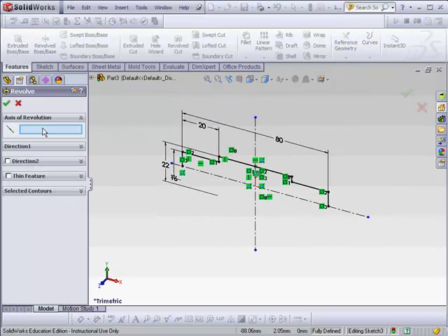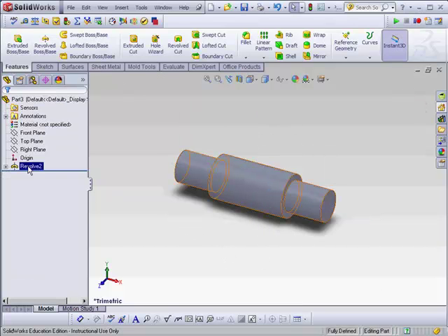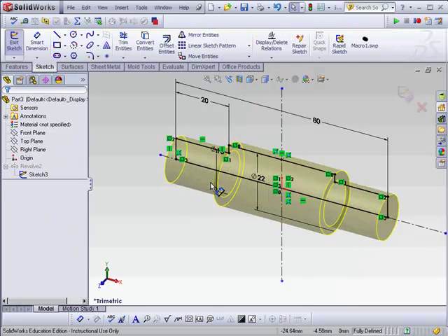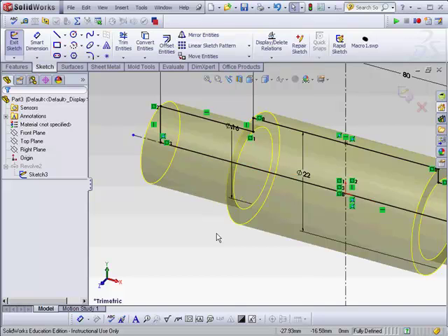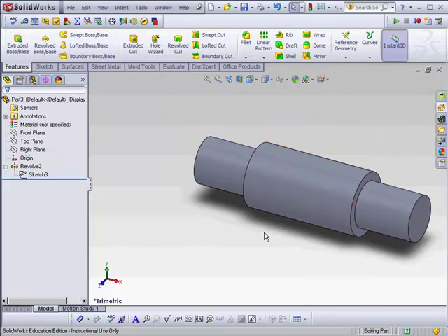It flips around like so. I pick the axis of rotation window, and the reason it's asking is because there's two center lines and it's ambiguous which I want to use. I pick this, it gives me the axle, it looks like so. But if I go back right now and I edit that sketch, you'll notice that even though I didn't close that sketch myself, a line was added so that it is a closed sketch, so that it is something that's going to create a solid object.